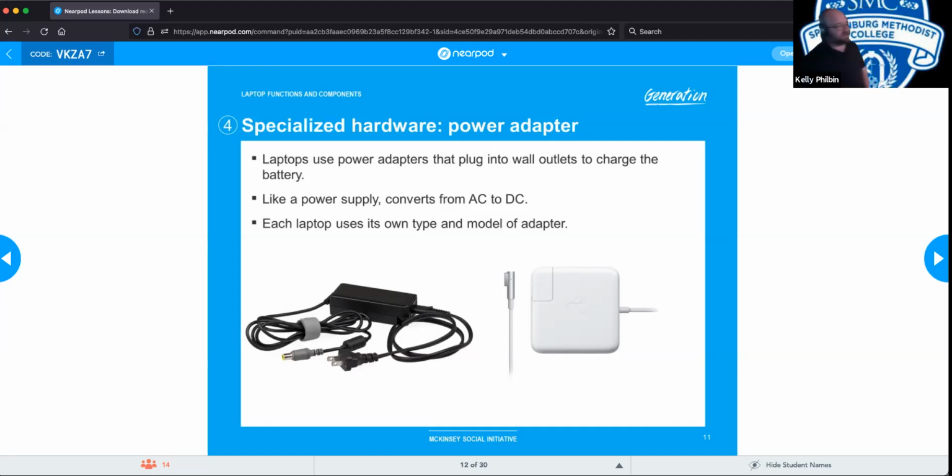And you need to be very careful of just grabbing one and using it on whatever you need. These things supply different voltages. So if you're not paying attention to it, just because the adapter on the end fits does not mean that that plug is sufficient for your computer. You could have too little juice and it won't function properly, or you can damage components, or it could have too much juice and you could literally burn out your computer or whatever you're hooking up to it. On the back of the little blocks, it will tell you the amperage and the voltage that it's supplying, and you need to make sure that that is compatible with whatever you're using it for.